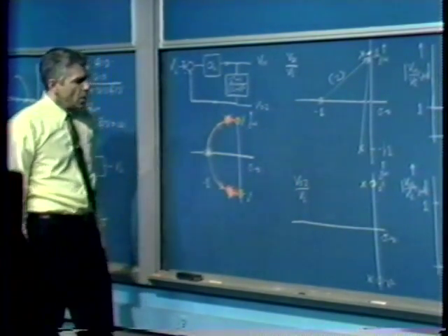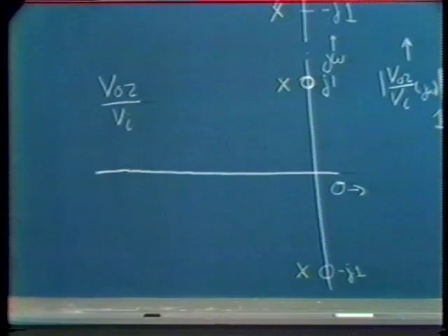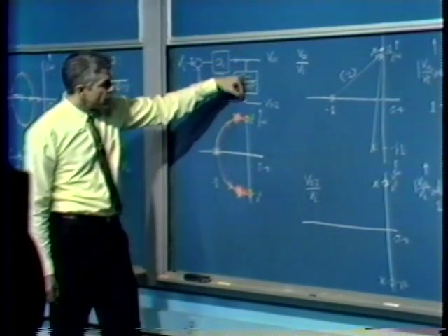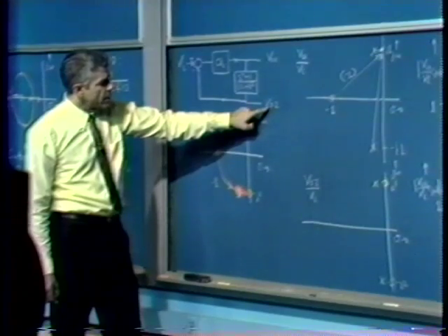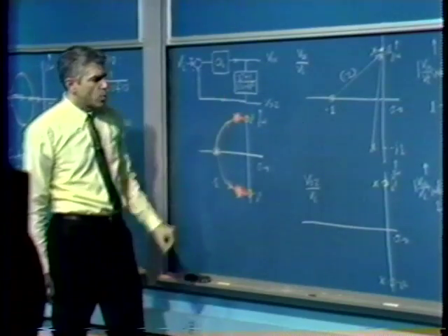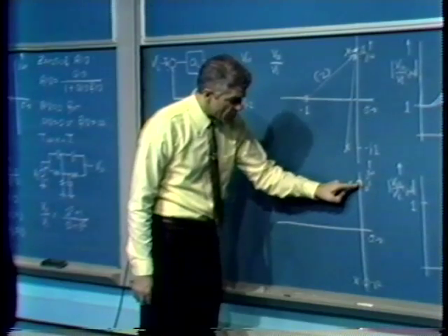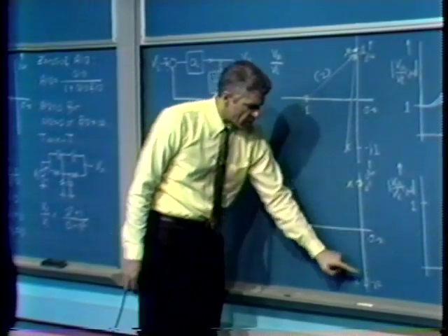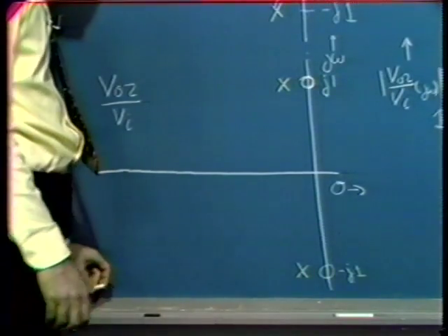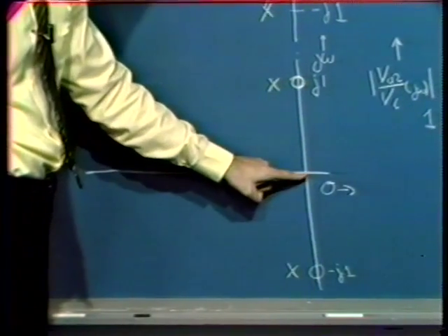function of input, we get exactly the same closed loop poles, we must, but now the closed loop zeros are those associated with the T network, because in this case the T is in the forward path, and so our Vout2 over Vi1 must include zeros at the zeros of the T network. And so we get this sort of behavior. We get the complex conjugate pole pair, and the zeros associated with that closed loop transfer function are those of the T. Again, at DC, the vectors from the poles and the zeros tend to cancel.